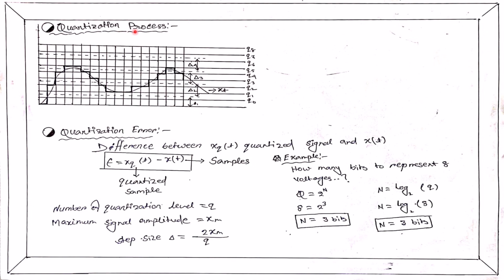Now we will see the quantization process. This means rounding off, for example, rounding 5.19 to 5.2. The quantization process is about approximating your signal. Here Q1, Q2, Q3, etc. are the quantization levels, and del 0, del 1, del 2, etc. are the ranges. This means that for all signals within del 1 range, we will call them Q0. Let's understand Q0. The midpoint of del 1 is Q0. In short, all signals that come within del 1 are rounded off to Q0. Similarly, all signals in del 2 are rounded off to Q1.